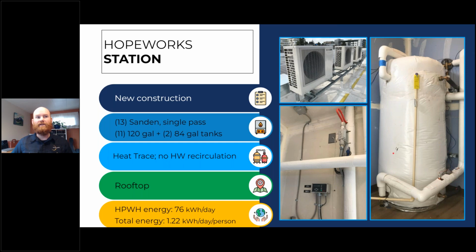And then because hot water recirculation, or temperature maintenance, as we also call it, is a challenge for this specific heat pump technology, we decided to implement heat trace on the piping, hot water piping. And so our temperature maintenance system, our hot water recirculation system, keeps that water in the piping hot because it's either circulating it or it's maintaining that temperature with an electrical element, like in this case. And that was definitely something that we designed in purposefully.